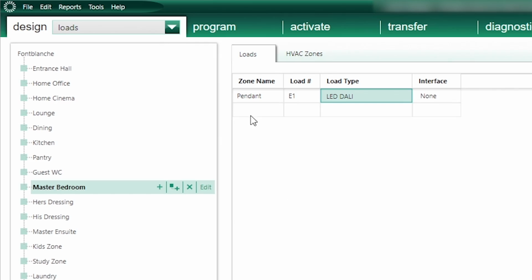So, in the early stage of the Lutron design phase, I'm going to assume, in this case for example, that I have one DALI driver per downlight. And because I have up to 64 possible drivers per loop, I should have plenty of space to accommodate more drivers than necessary, especially on a residential project. So, back in my database, I'll add downlights with circuit ID E2 and load type DALI LED.